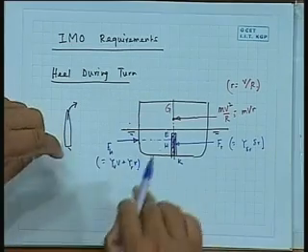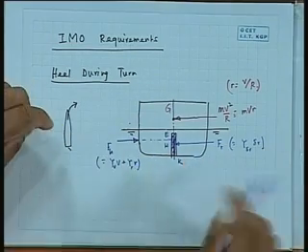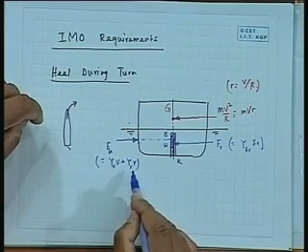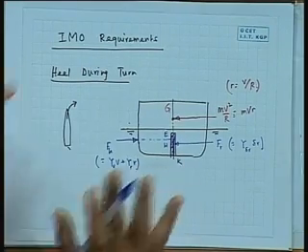Basically Fh is the Y force on the hull, and the hull Y force is because of dY by dv times v and dY by dr times r, because it has got only v and r, it does not have v dot and r dot right now. In the case of the initial phase, you will have v dot and r dot. I will come to that afterwards. I am looking at heel during turn, which is a steady turn.